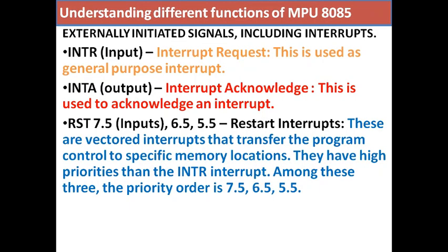The microprocessor will temporarily suspend its present work, acknowledge the interrupt, do the necessary work for it, and again get back to its original work. Now whenever an INTR is requested and the microprocessor suspends its own work and is ready to work for it, INTA is generated, that is the interrupt acknowledgement.